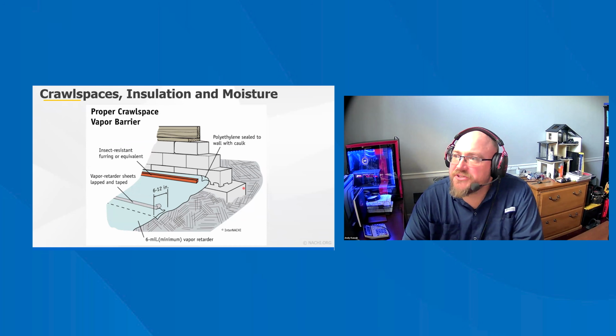The primary causes of moisture problems in crawl spaces include poor site drainage, lack of a ground vapor diffusion retarder, improperly installed insulation, and crawl space ventilation during humid summer conditions. Crawl space moisture damage and mold formation can be caused by any one of these issues. Therefore, these issues should be checked during an inspection.